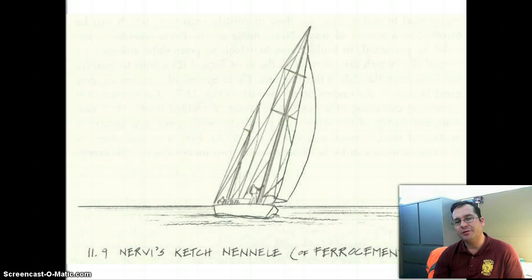One of the interesting things you see in some of the concrete canoe devices is that they'll use a very, very lightweight aggregate. And that's basically to reduce the mass of the canoe. That means it needs to displace less water, and for competition purposes it can be paddled through the water more quickly.